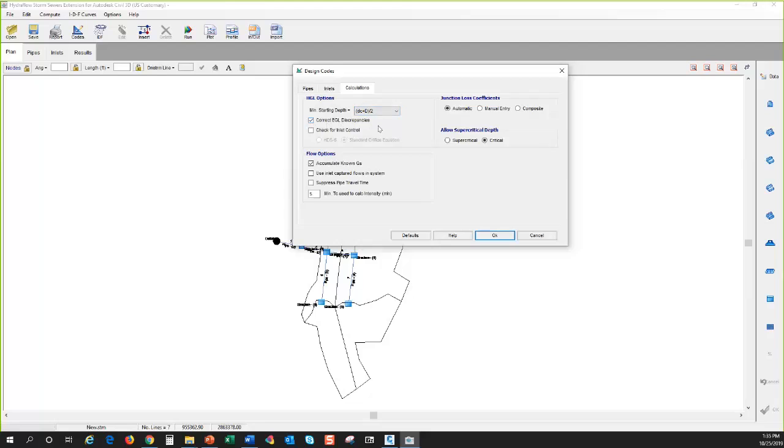looks to me like what it does is when you've got water coming into an inlet or a structure from multiple sources, and that combination of flows coming in creates a second hydraulic jump at that inlet, it goes up. And I've got an example I can show you where I kind of demonstrated that to myself, how it works. So I usually check this, but I know there are people that have asked how this is being calculated, and I'm looking into that to try to see exactly how that's calculated. It should be based on something in HEC 22, and I'm trying to see what that is.